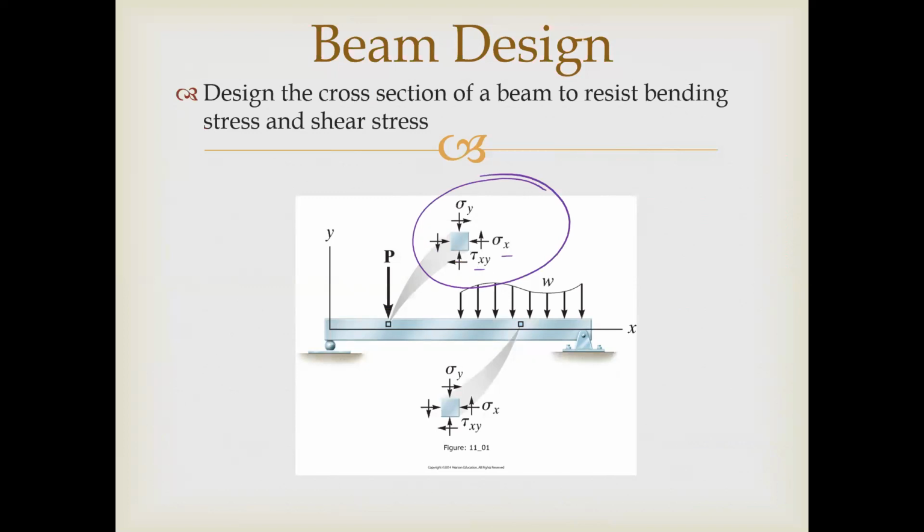And you, in theory, also have this vertical stress, sigma y, that is going to have a larger value right at the point of application. We often just completely neglect that, but where you place that load, you will have some stress acting in that beam. But it typically is far less than the longitudinal stress that we're designing for.